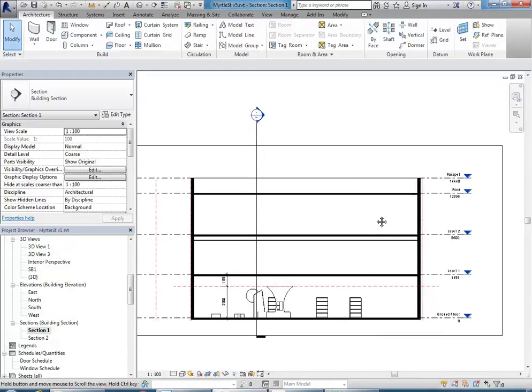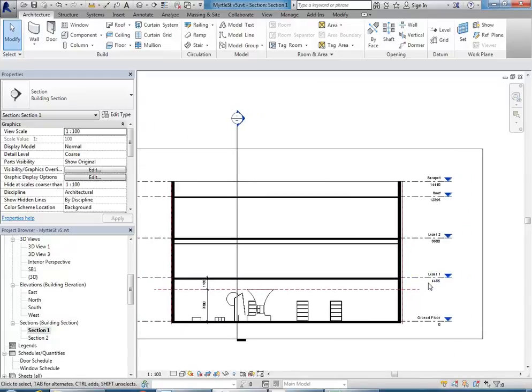And this really is one of the best features in Revit, the ability to easily adjust levels as you work through your projects. I've had lots of projects with a few different floor levels and then many stories, and I'll just roughly get the levels in that I know I need and worry about the actual values for those heights much later on, often when I get close to construction stage. When I'm going through the planning and approval process, I'll just make sure that the envelopes, the tops of the buildings, are pretty close to being right, but then you often won't refine all of the levels close to the ground until you've got the site fully worked out.